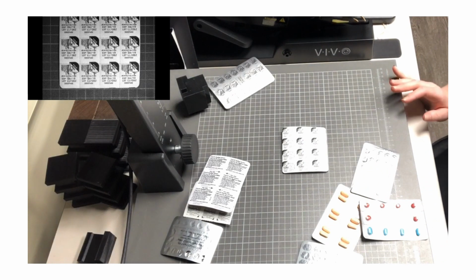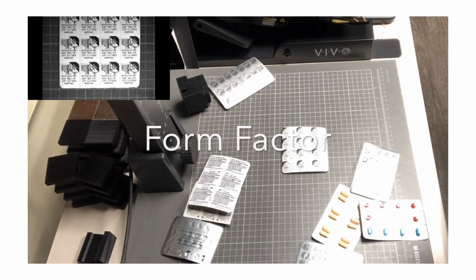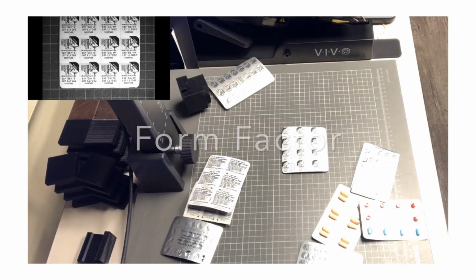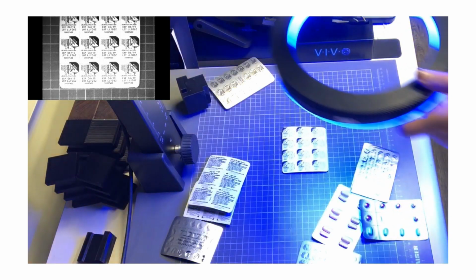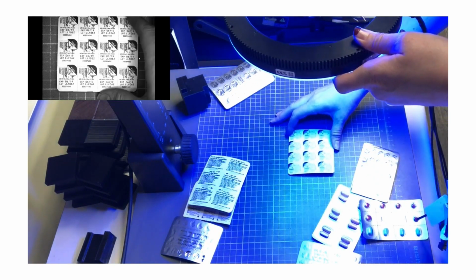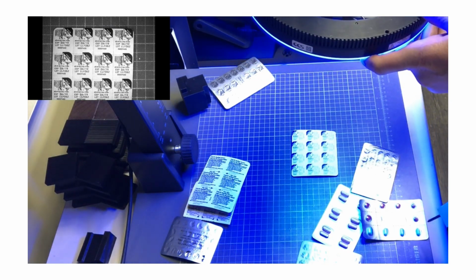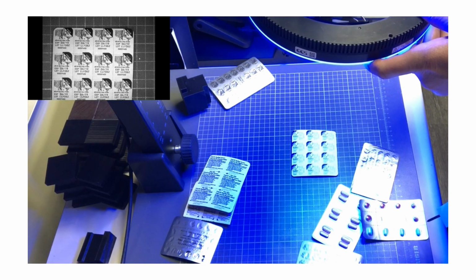Just starting off with a typical bright field light. We'll start with just a ring light. I love to start with an HPR2 because I can move the sample up and down. When it's in a low position, it works like a low field or a dark field light, and when it's in a high position, it works as a bright field light. So here I've just added a blue light right now, but it's a white sample, so the color doesn't really matter in this scenario.